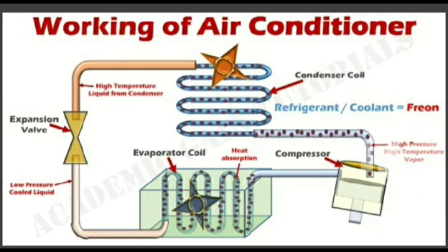These evaporator coils are very important to an air conditioner. The evaporator is the indoor air conditioning unit we place inside our home, where the air conditioner actually picks up the heat from inside our home. The copper tubes of the evaporator receive the depressurized cold liquid refrigerant from the expansion valve, and when our indoor air blows over the cold coils, the heat from inside the home gets absorbed by this cold refrigerant.